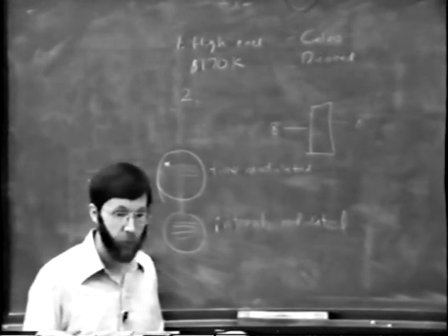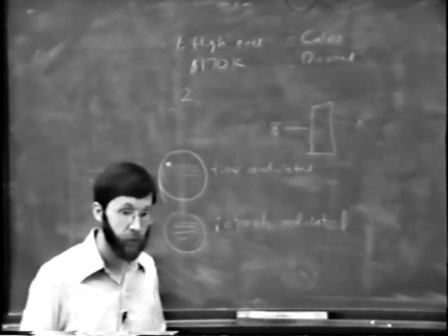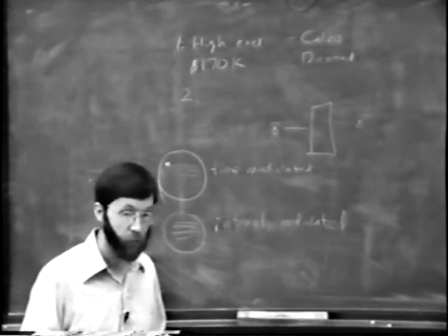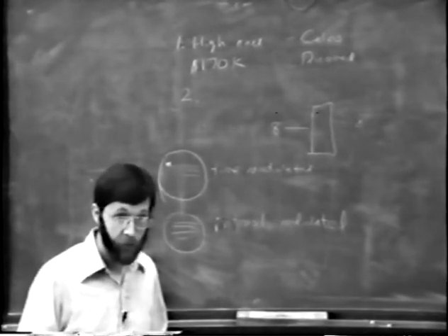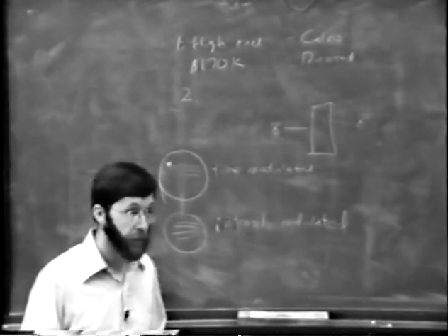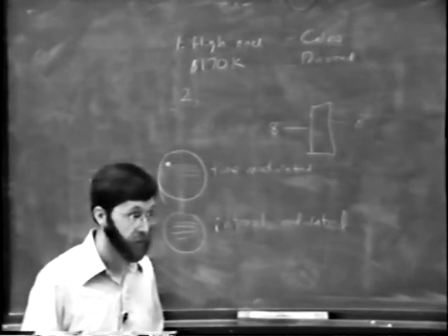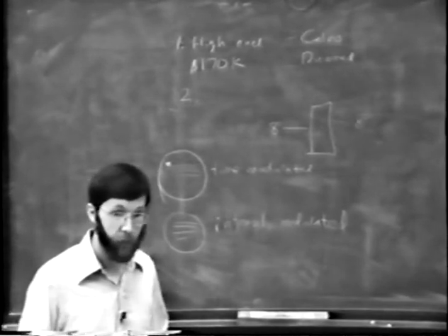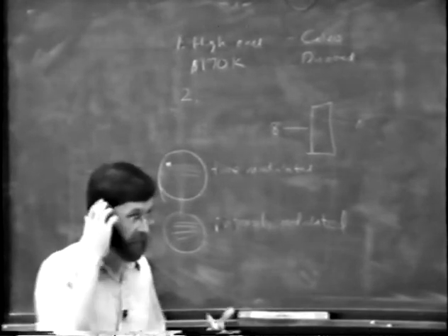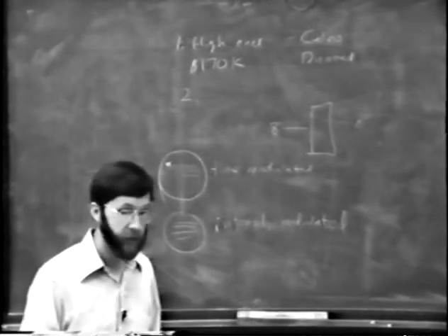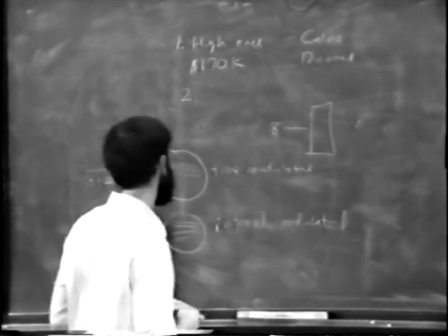The actual way that we would calibrate it is to take Polaroid film and expose a step wedge on the Polaroid film. Now, Polaroid film itself is not very stable. But a fresh batch of Polaroid film, if it is fresh, is in fact more stable than that analog circuitry. All right, and that's sort of a measurement. You don't have to be perfect, but it's better to have something to measure the light out.